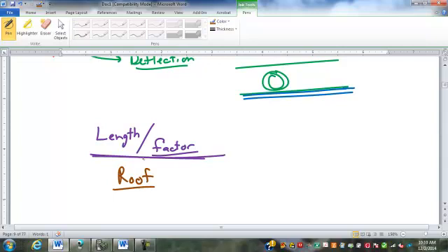Floor beams, ordinary usage for live load, it's L over 360 they're listing. If you have tile floors or any sort of a hard floor like that that is susceptible to cracking, you usually change that to an L over 480 so you don't crack the grout lines in your tiles and stuff like that. I have actually seen floors that flexed enough because it was not specified in the design stage that they wanted tile floors.